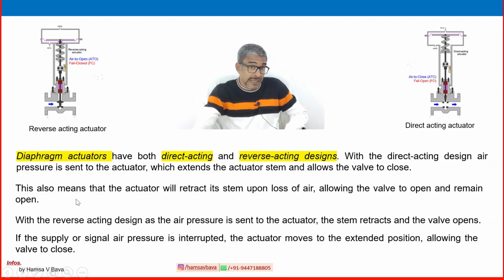So both direct acting and reverse acting are a safety concern. In case of abnormal activities such as air failure, electrical failure, or any ESD activated, this valve will go to its normal position, fail to open or fail to close.